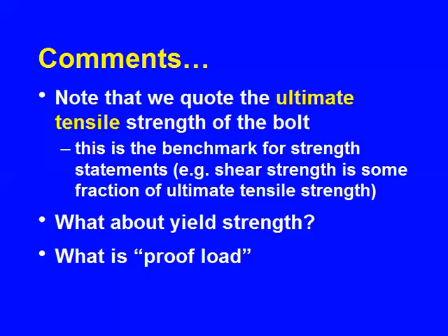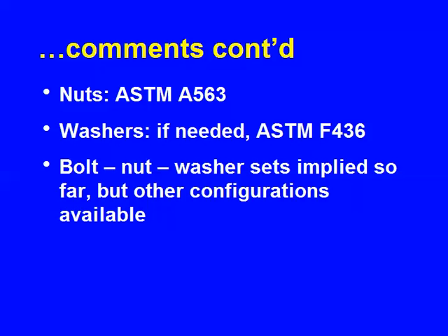Nuts, obviously we're going to need nuts. The ASTM spec for that is 563. As far as we are concerned, once you've picked the nut that's consistent with that fastener, let's say you're using A325 fasteners, that specification will tell you which nut to use, or which nuts. I think you've got a couple of choices. So once you've done that, you have a nut that will not fail before the body of the fastener fails. So that's all the design that's involved in that case. We don't do the design. That's been done. It's historically available, and we get on with it.